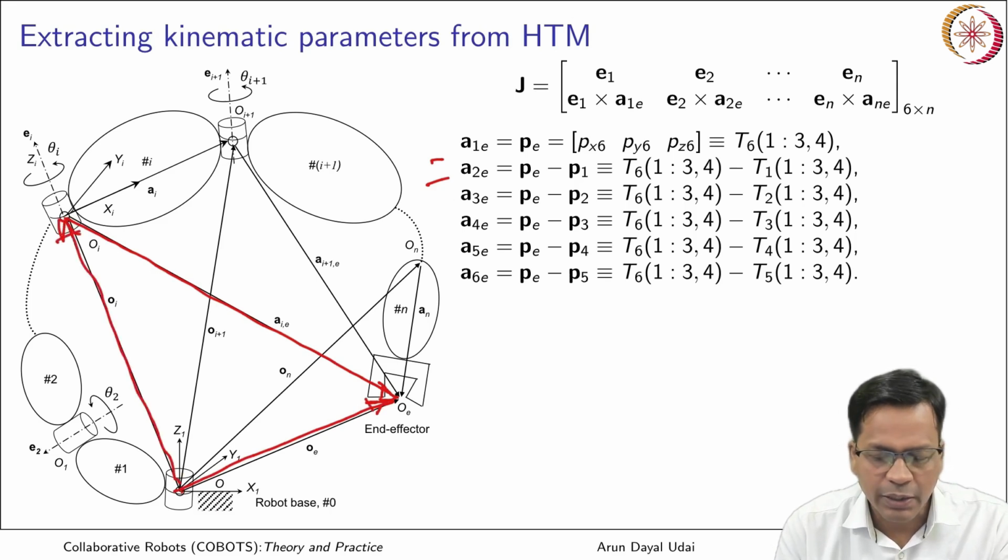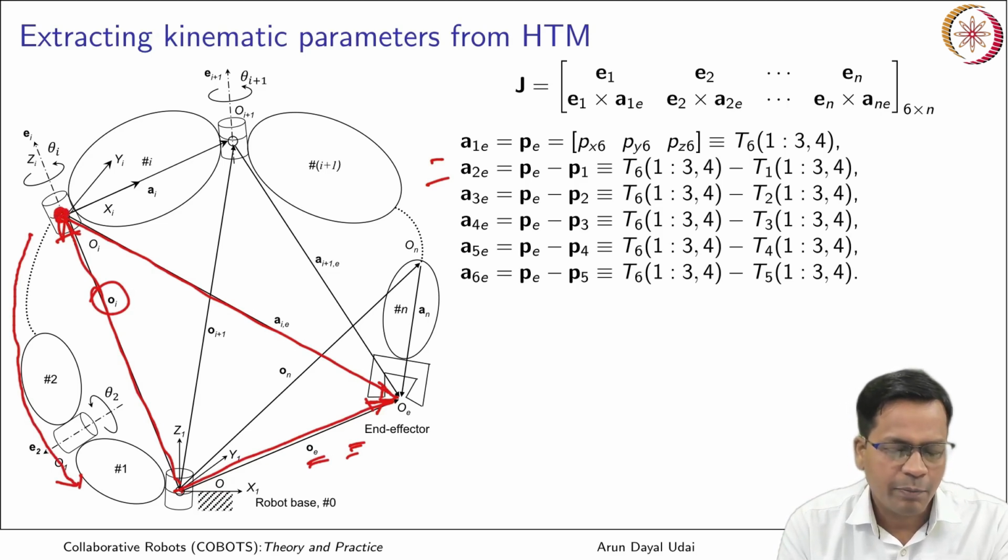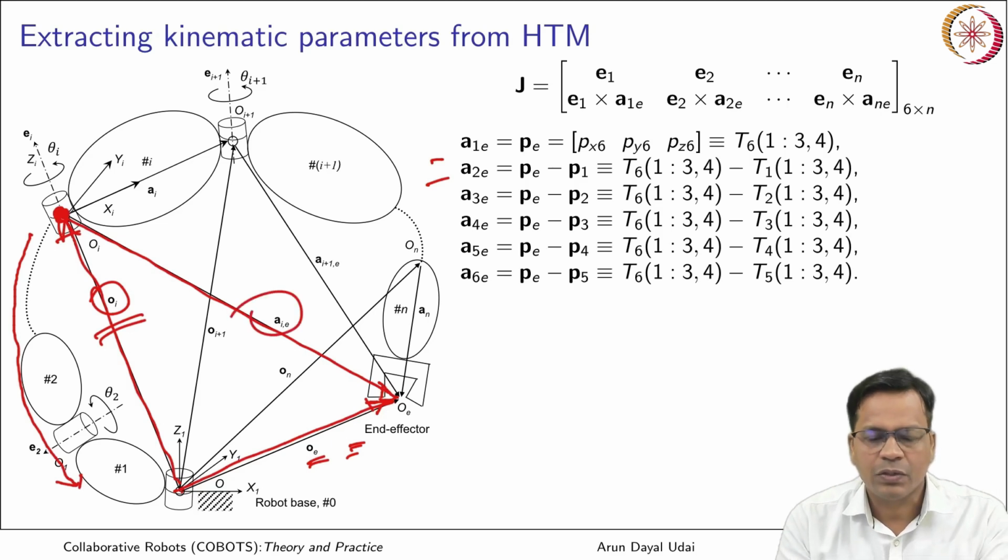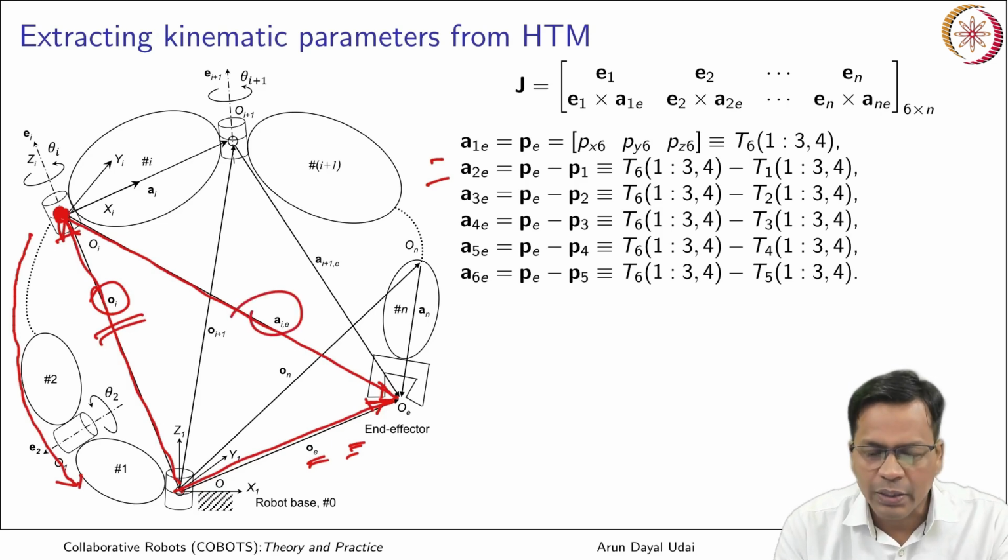This is nothing but the end effector vector. This is obtained from all the Ais which are here, from here to here. If I take the product of this, whatever I get, the homogeneous transformation matrix for this joint Oi, from there I can extract this one. So using this vector triangle I get this. For all the links I can do it in a similar way.